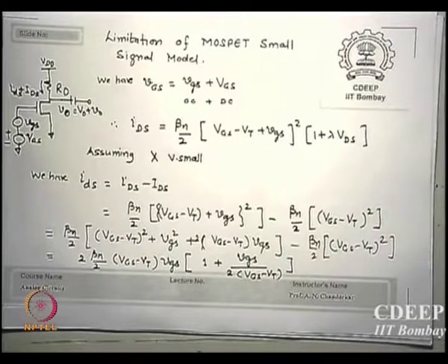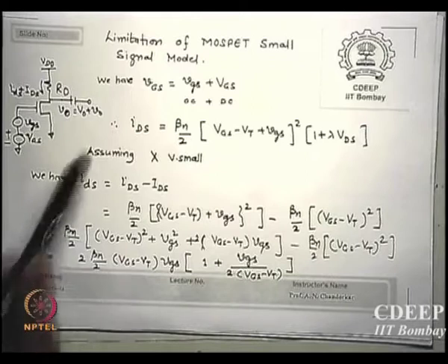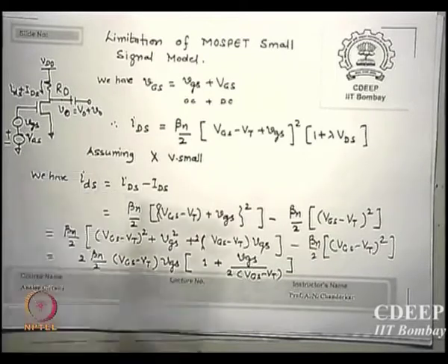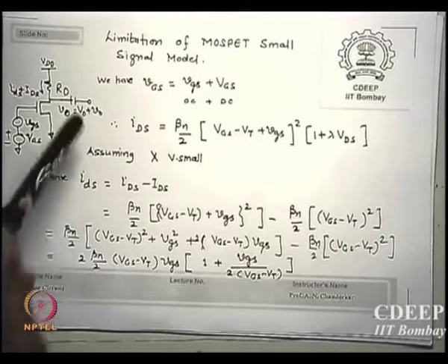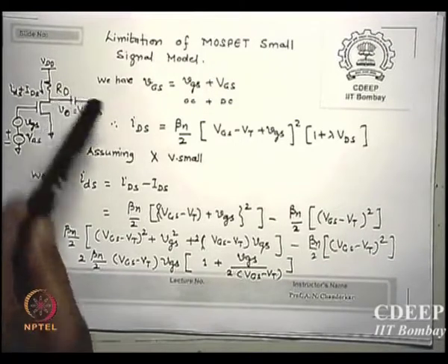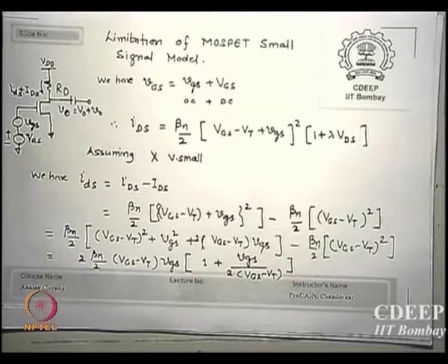Superposition. So a DC signal is superimposed by an AC signal, and we expect the output voltage also will have two parts, DC part and AC part. And if I want to get rid of DC, what should I do? Put a capacitor, then only AC will pass. That is what amplifiers will do later when we only look for small signal AC outputs.